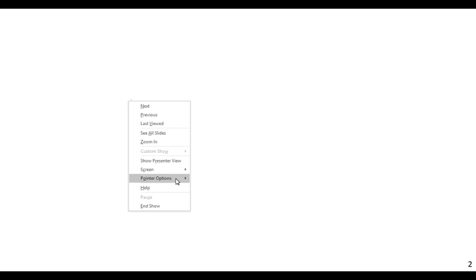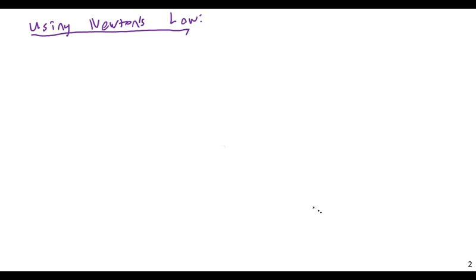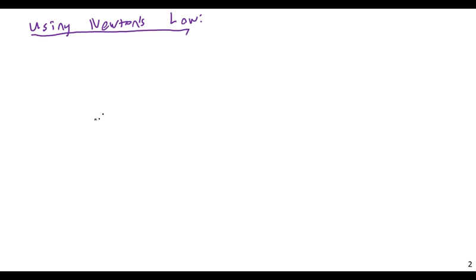Okay, so I'm going to use this, and I'm just going to use Newton's second law and go through a few simple derivations and see what happens. Newton's second law, of course, being the sum of forces equals mass times acceleration, which you remember from mechanics of materials and from engineering statics and from physics classes before that even. All I'm going to do is add up the forces on each plane. And remember, each of these P's is a pressure, so in order to produce a force value, I need to multiply it by a certain area.